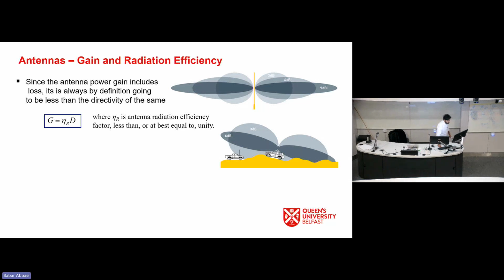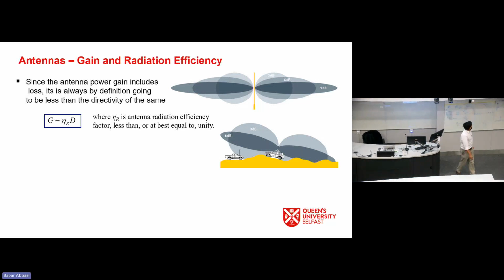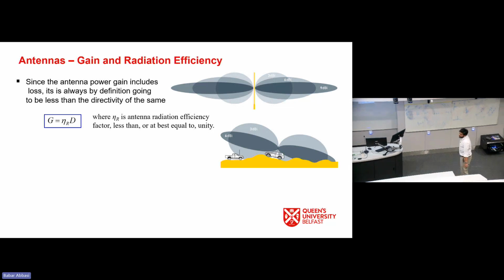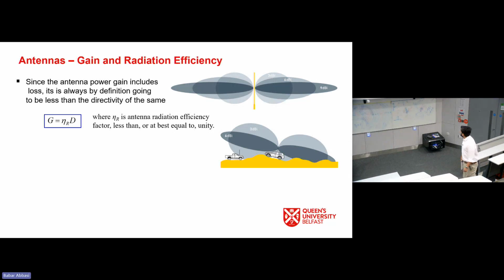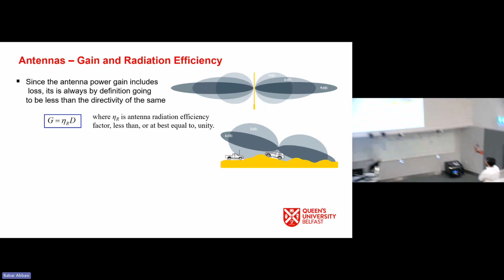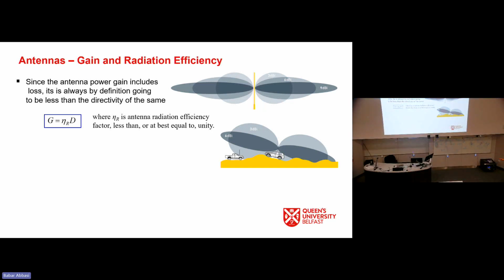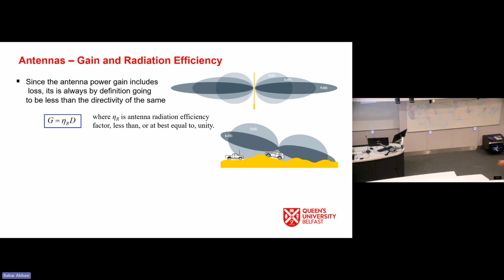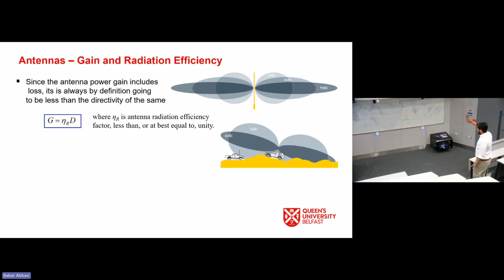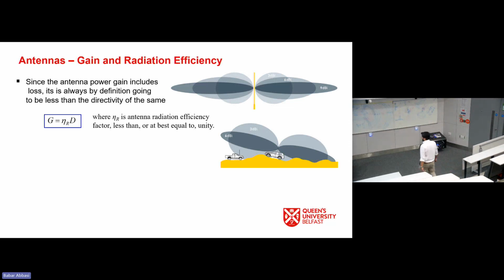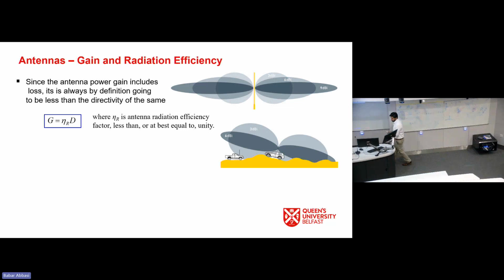So this is what I have just mentioned. Gain is efficiency times directivity. This is another example of why we really focus on gain. If we have 3 dBi of gain in a car with a simple antenna, then 3 dBi of gain with more coverage is sometimes better than an antenna with extreme coverage but less sectoral coverage. So it's very application specific. It's a complete new field for the engineering domain. There are different antennas for different purposes.